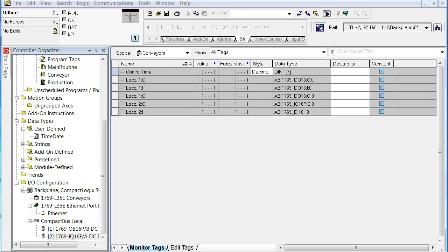There was a time when it mattered in some of the older chassis, and you had some convoluted hardware structures called complementary I/O, which is covered, by the way, in one of the lecture series, talking about the original rack of memory back in the PLC 2 and 5 days, 1771 I/O chassis, etc. That's no longer an issue. You can pretty much put anything anywhere you want. You do have to be conscious of current draw and load, but you're not as limited as you used to be.